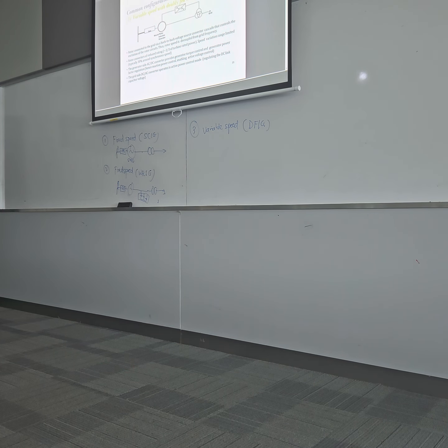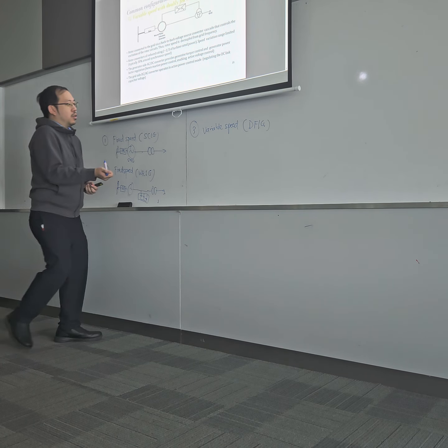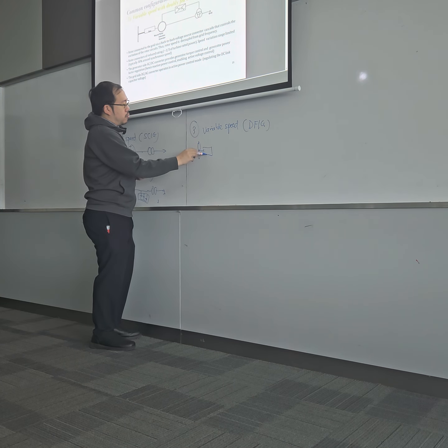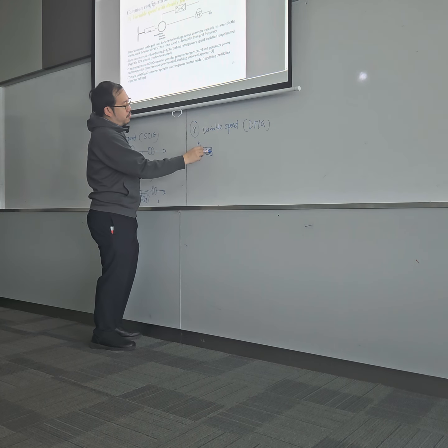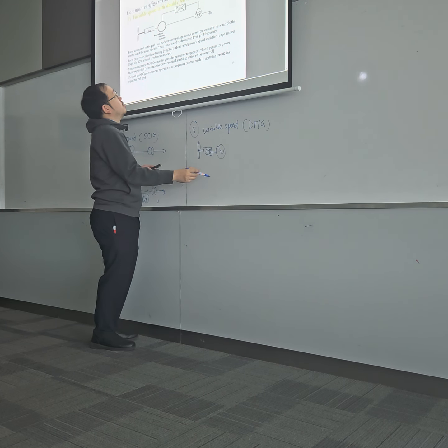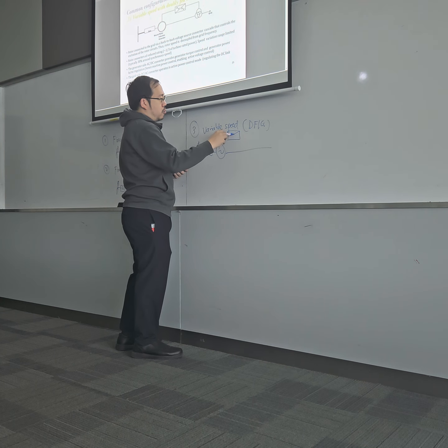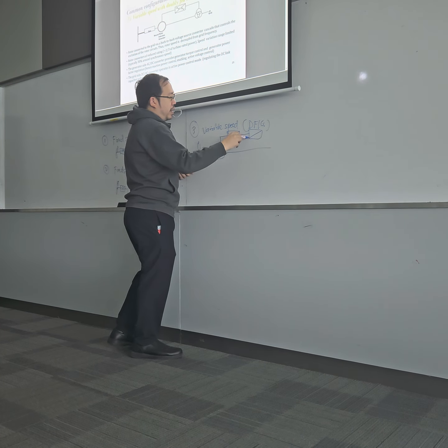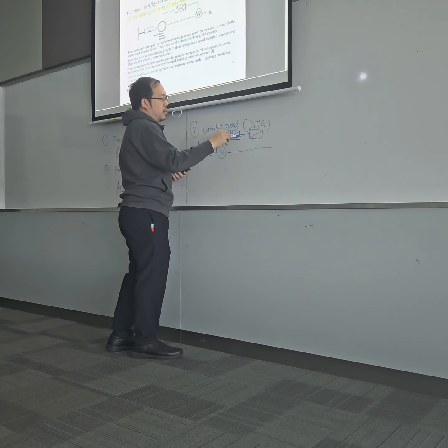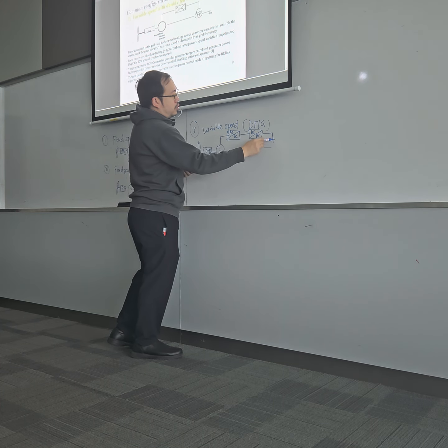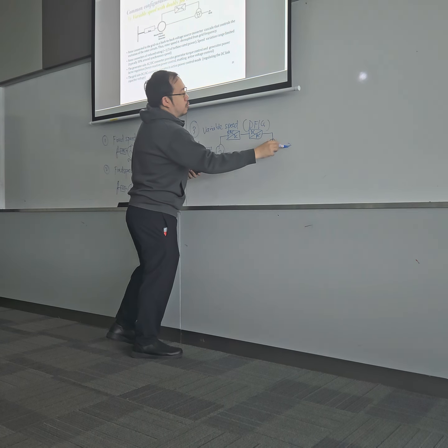So you have your generator AC-DC converter to provide the torque control. I'll show you what this means. You have the gearbox. Then you have your generator. Over here you have your back-to-back. Back-to-back here means AC-DC and DC-AC. Okay? And then back to the grid.